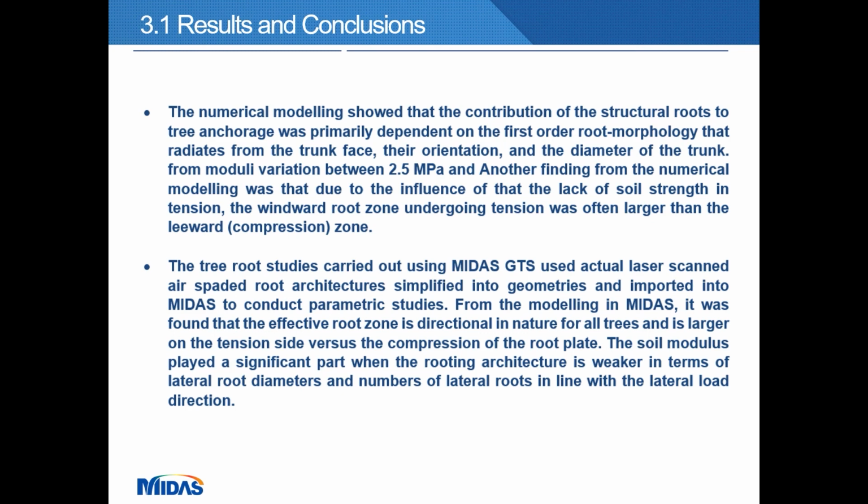We also found that the direction of the rooting zone in natural trees is larger in tension, as I said before, and the soil modulus also plays a significant part when the rooting architecture is weaker in terms of lateral rooting diameters and the number of lateral roots in line with the lateral load direction.